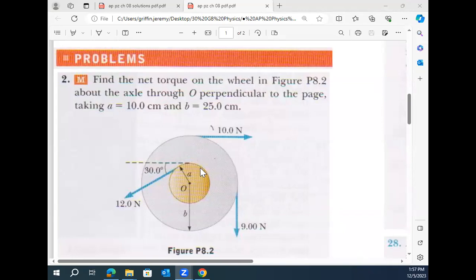And 3 forces. It looks like this top force is pulling clockwise. This downward force is pulling clockwise, right? And this one on the left is actually pulling counterclockwise. You guys see that, right? I think there's a couple ways to interpret this that might lead to slightly different answers. So it's R cross F is the torque, right? In different directions, you have to have some kind of subtraction. I'm going to call clockwise negative and counterclockwise positive, as I usually do, right?